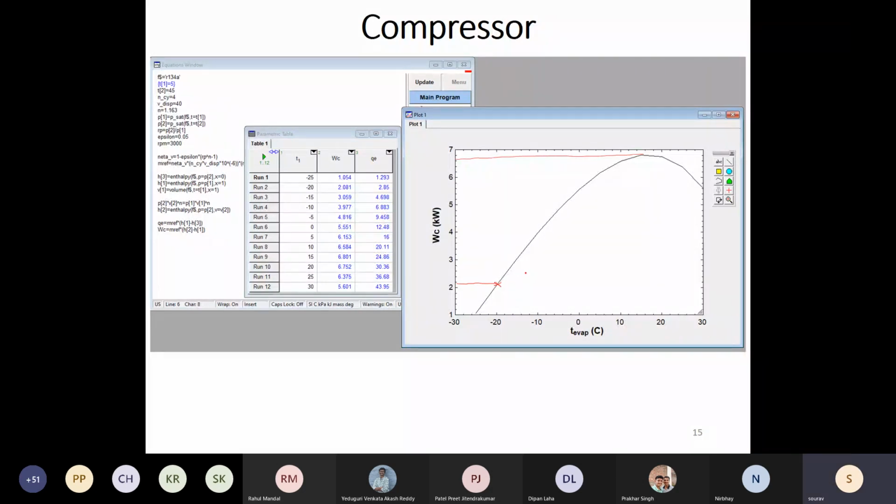Now, fortunately for ACs, you will see that you will most of the time be operating over here. Anyhow, even there you would have to size your compressor for this evaporator temperature, and it is quite close to your minimum rated temperature. Most of the ACs will come with a minimum rated temperature of 16 degrees.